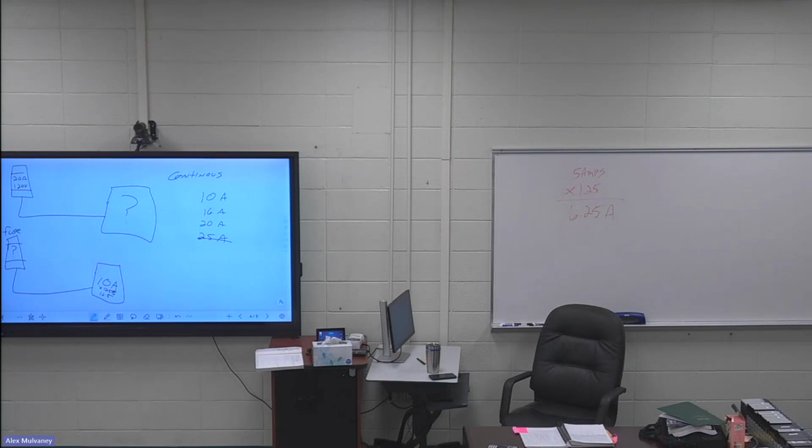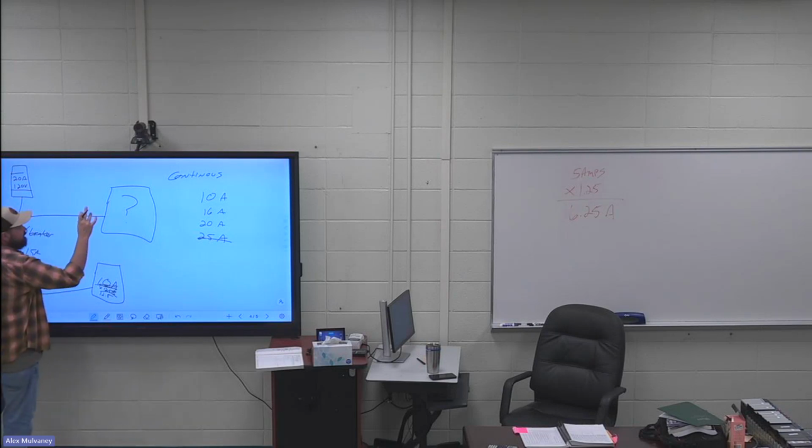What's a standard size? Just guessing. Just give me your best guess. What's a standard size fuse that would accommodate 12.5 amps? 15 amp fuse, right? So if I don't know my fuse or breaker, that's where I have to take my load times 125%. But if I know my load, or if I know what size I have for my fuse, I have to derate what I can connect to it because it's a continuous duty load.